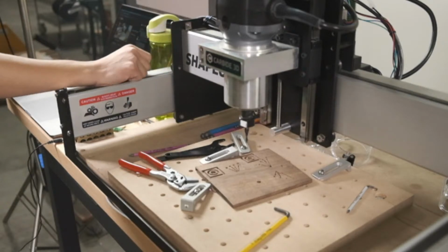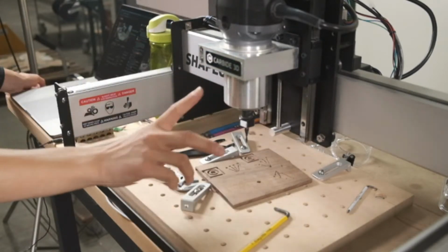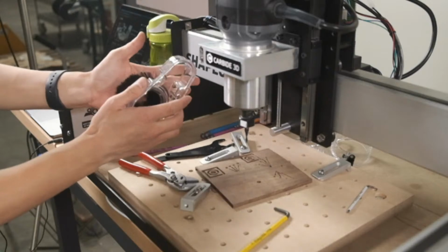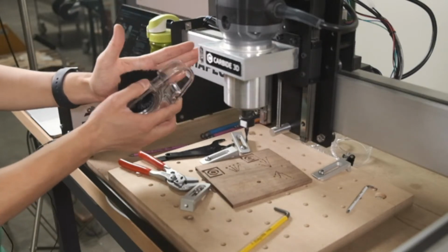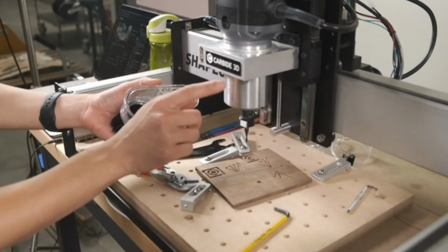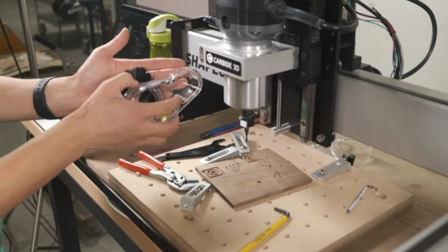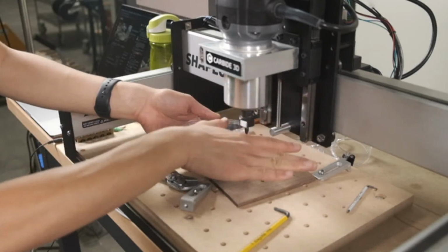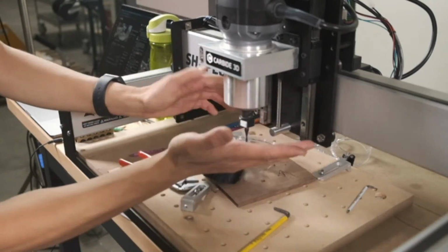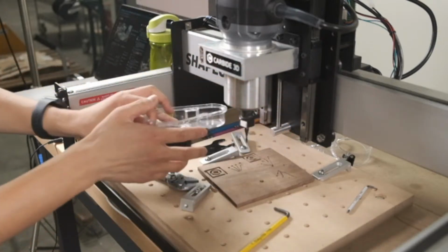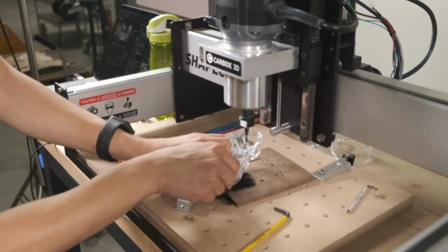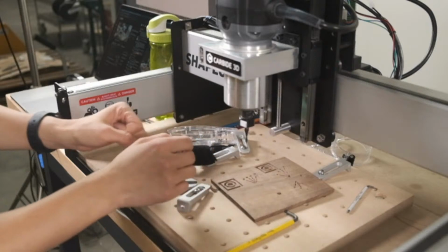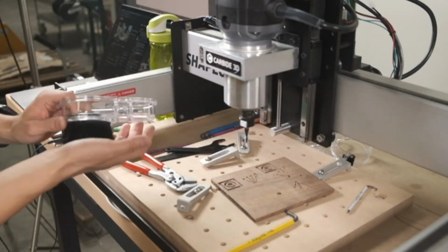So dust boots, sometimes they do cause issues when you have stiff bristles, which we are working on sourcing some really soft bristles that are easy to crush, that won't apply resistance to your machine spindle or gantry. But if you have really stiff bristles that are hard to crush, as you're bringing the spindle down, the bristles are actually pushing the whole machine up and twisting it or torquing it. If you have a brush that's really crushed into the workpiece when you're trying to surface it or face it, it's going to twist or tweak the machine and give you some off-character cuts.